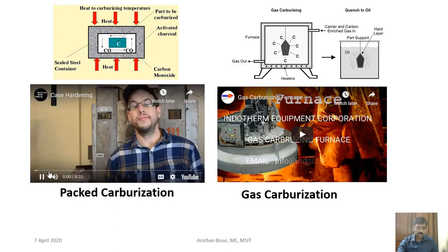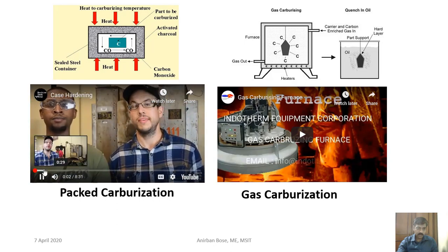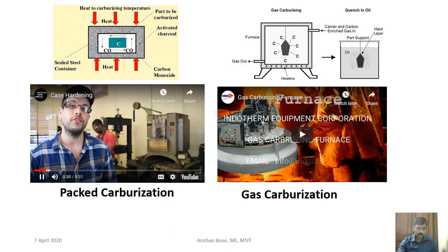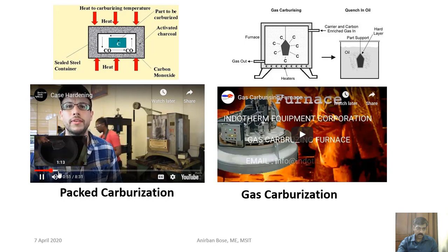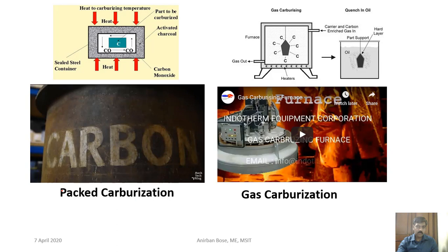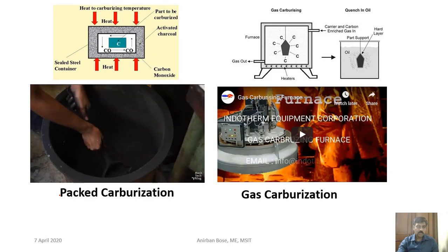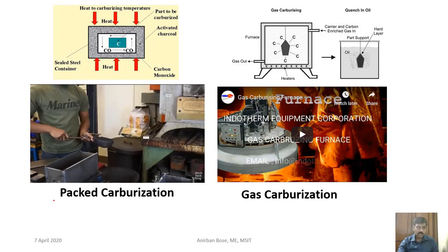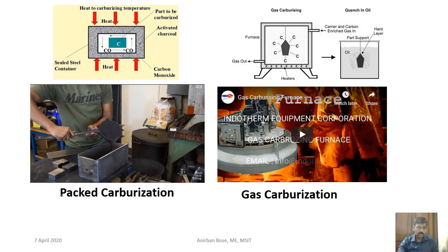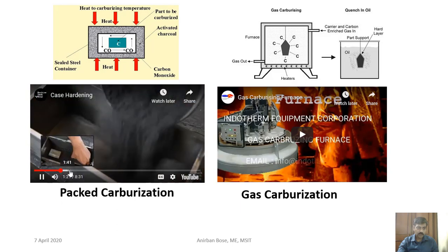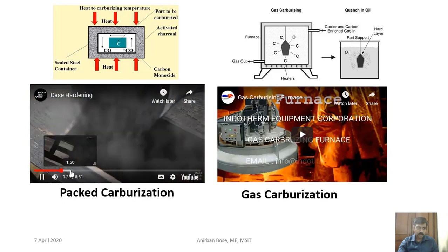In fact, carburization. I'm Ann. And I'm Todd. It is one of the most common projects for machinist apprentices, making steel more wear resistant. Here you can see the charcoal powder being packed in a box. Lay down about an inch of carbonaceous material in a steel box with a tight-fitting lid.